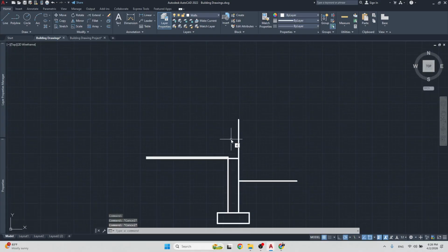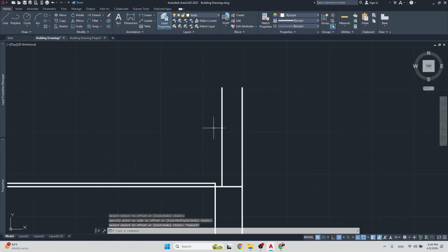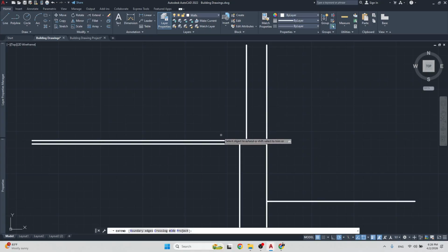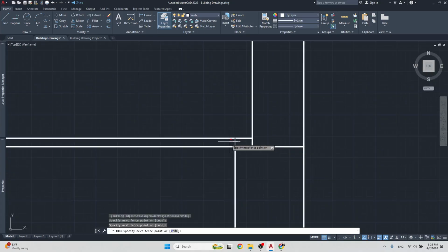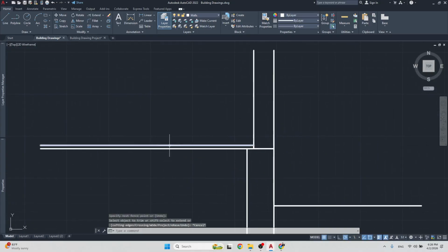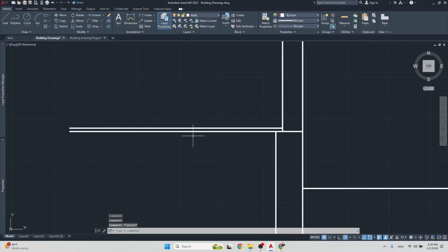So this wall is a 6-inch block, so we're going to put 150 millimeters, right? 25 millimeters is 1 inch times 6, 150 millimeters. So this is going to be our external wall for our house, and then we are going to just extend this across to meet it. And then I could just clean this up by trimming out right there. So we could see this is the finished floor, and then below that we're going to have our 4-inch concrete slab.